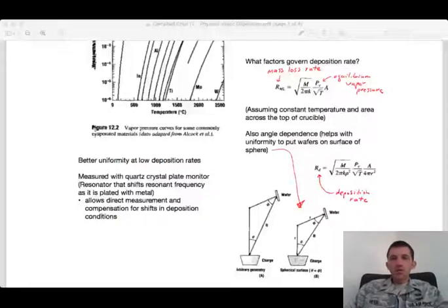And then you've got some constants in here, Boltzmann's constant, which is reflective of the fact that you are going to be losing atoms from the tail that have the highest energy, and so the distribution therein is important. The mass loss rate will be higher for atoms that have a higher equilibrium vapor pressure to temperature ratio, right?